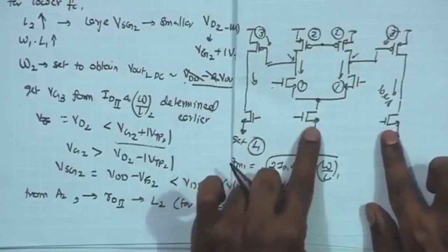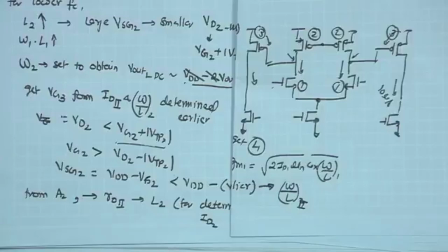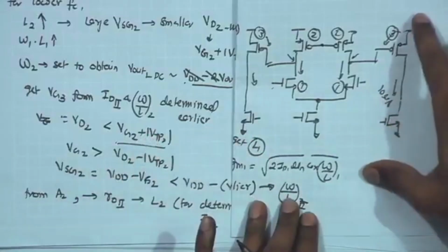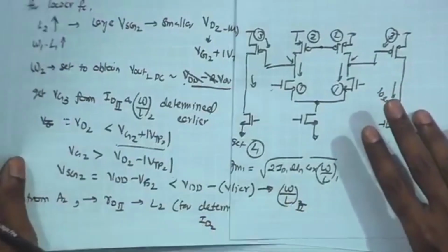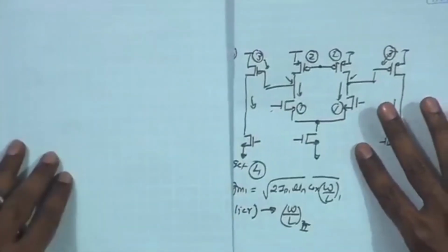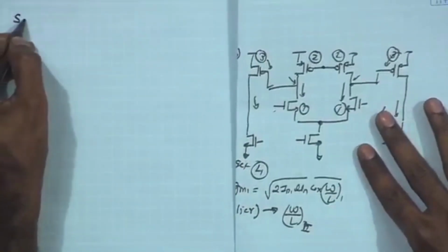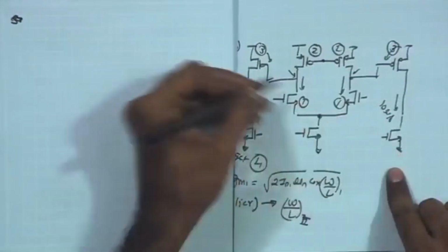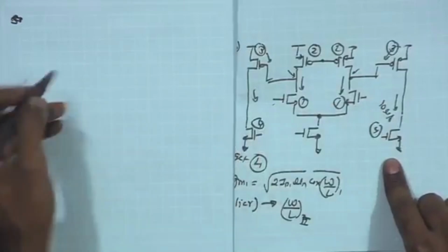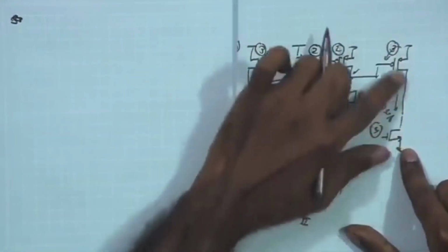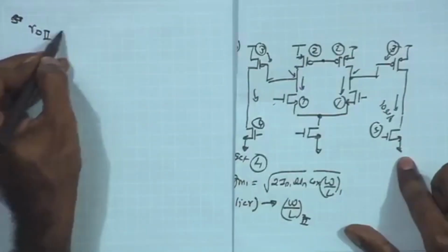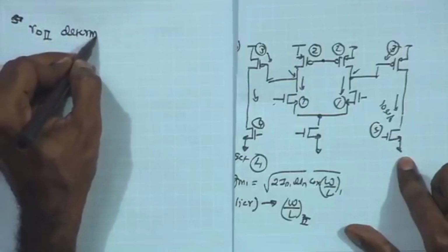Now the next is the question of these NMOS devices. So for NMOS devices, once again the channel length should be similar for the second stage. For this, if I look at the second stage, if I call this say 1, 2, 3, 4 M4 pair, that means I am calling these two as M4. So once again the RO is determined, I is determined for a gain requirement. Therefore the RO2 determined earlier